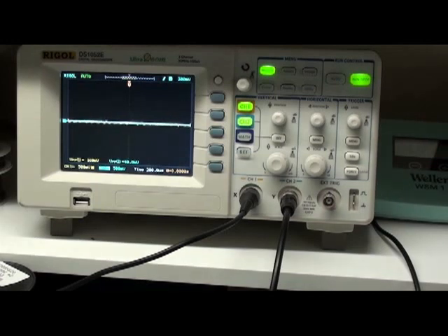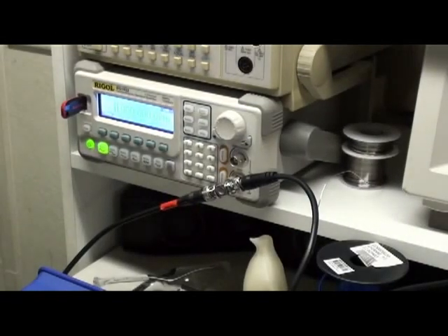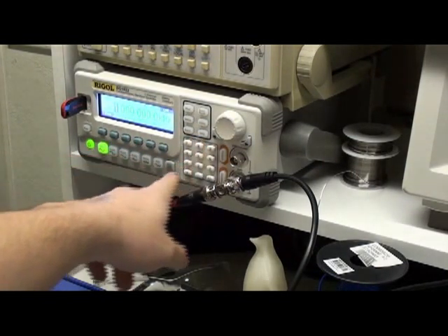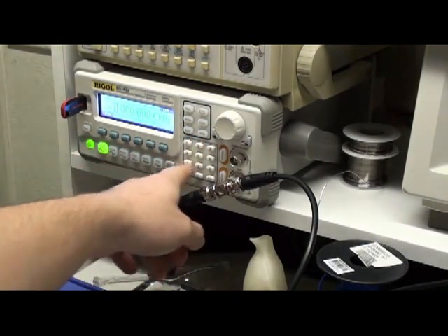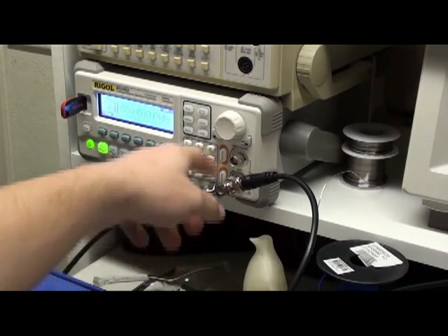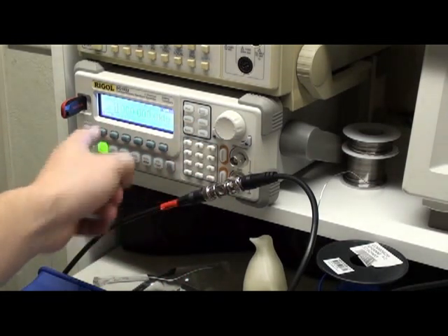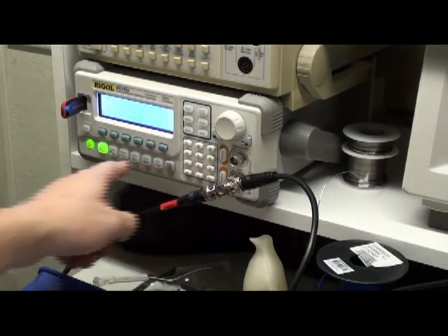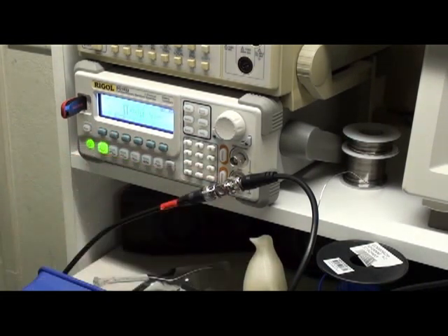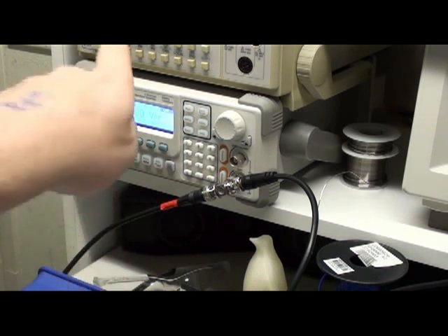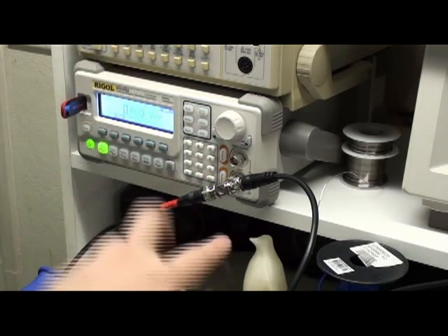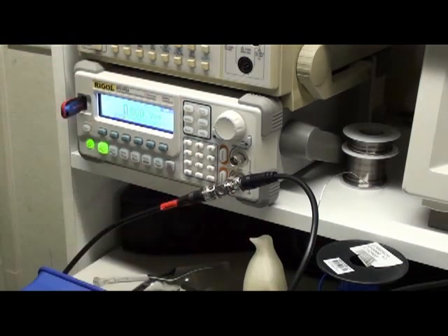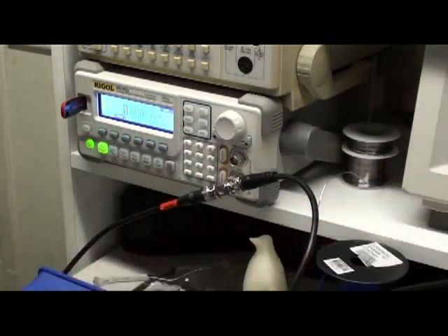So now, just to quickly show you, this is my function generator. It's got a bunch of keys. You can change the mathematical function you want to put in, you can change the frequency, the voltage, whatever you want. In fact, right now I'm going to change my sine wave to 1 volt peak to peak, which means from the top to bottom will be 1 volt, and then it'll keep going forever and ever at 1 kilohertz.